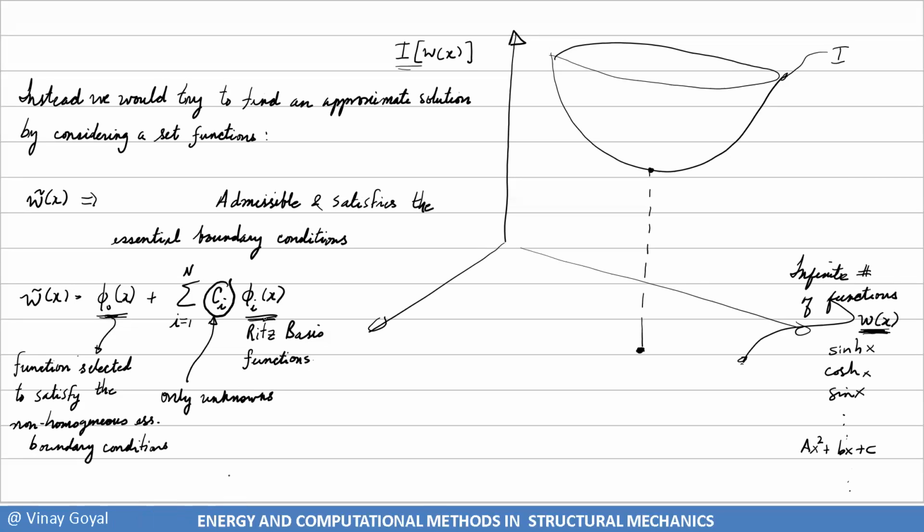And so what I've done then, if I look at my graph to the right, this functional I depends on what function W I select. And so I construct this surface, which comes out as a quadratic functional. This is your quadratic functional. And we know a minimum exists if the system is self-adjoint. So we know there's a minimum, and that minimum is this one. That's the exact solution to the problem.